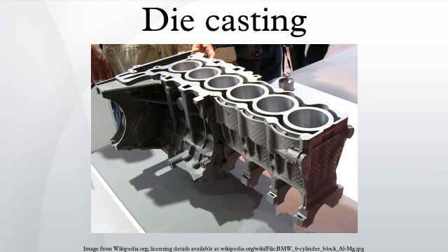The thermal analysis was the first done for any casting process. This was done by creating an electrical analog of the thermal system. A cross-section of the dies was drawn on Teledeltos paper and then thermal loads and cooling patterns were drawn onto the paper. Water lines were represented by magnets of various sizes. The thermal conductivity was represented by the reciprocal of the resistivity of the paper. The Acrorad system employed a bottom fill system that required a stable flow front. Logical thought processes and trial and error were used because computerized analysis did not exist yet. However, this modeling was the precursor to computerized flow and fill modeling.